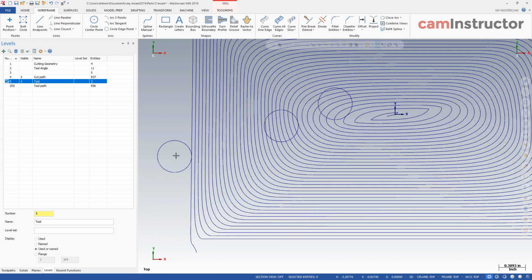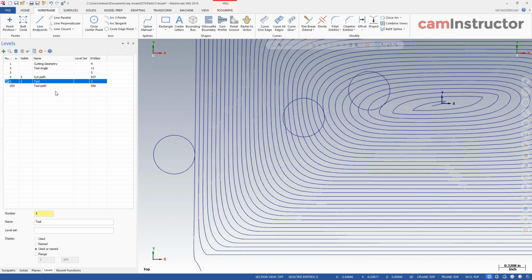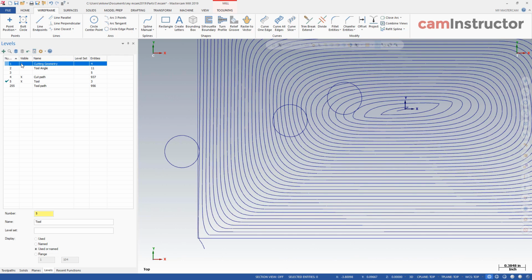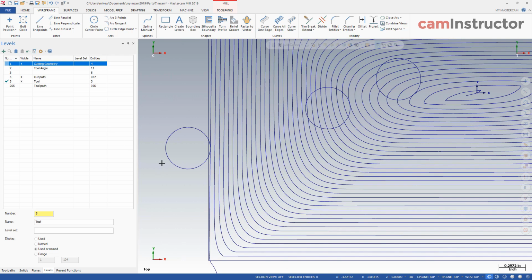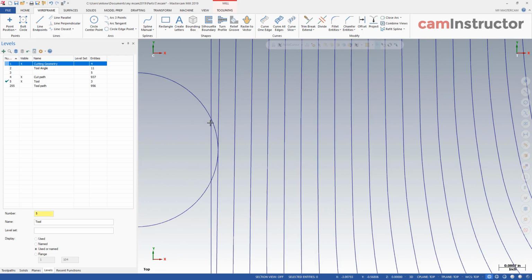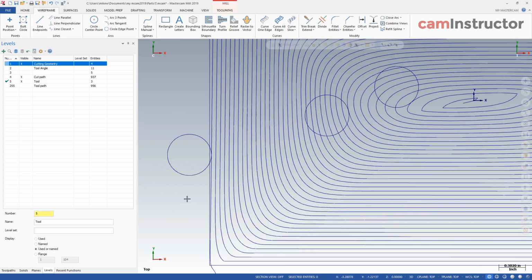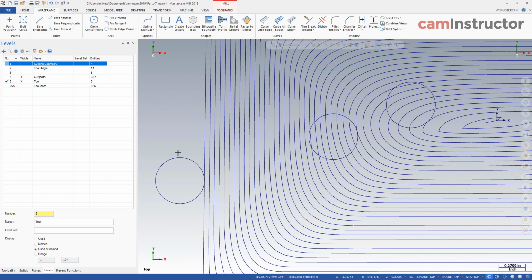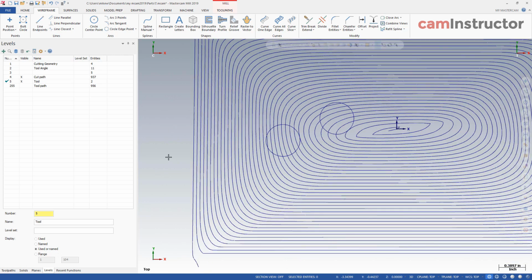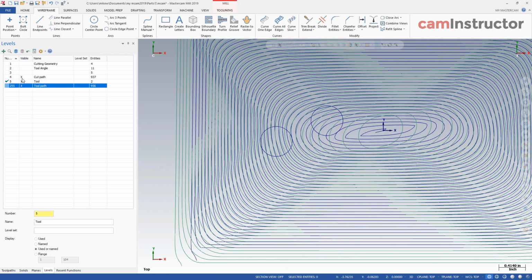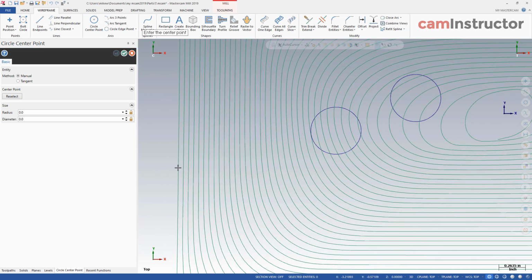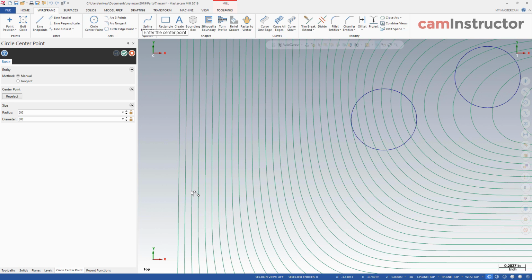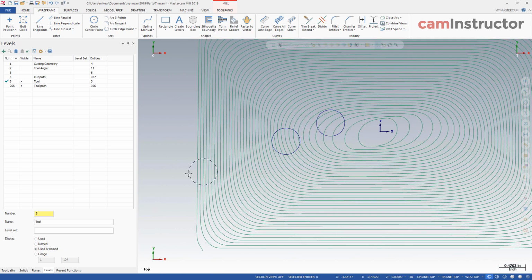I guess what I'll have to do here, since I placed this circle on the very first cut, is turn on the cutting geometry to set up the stock for that cut. It's not going to be accurate because typically, I've offset and it's still not at full depth over here. So this is not going to be a good example. So maybe I'm just going to omit that one for now, and I should do one maybe slightly inside. Let's go to, say, this line here. Okay, so that's going to work much better.